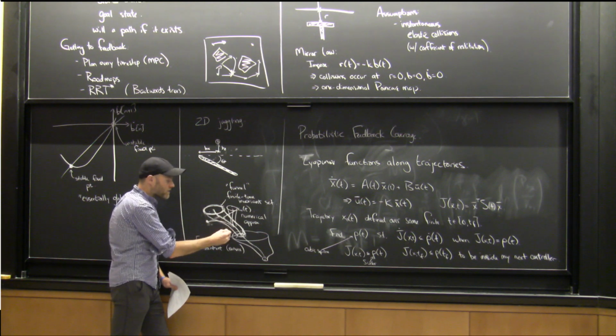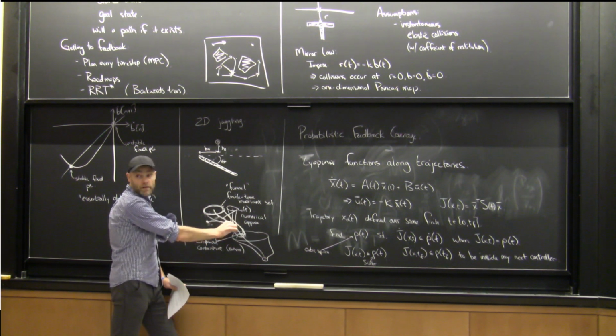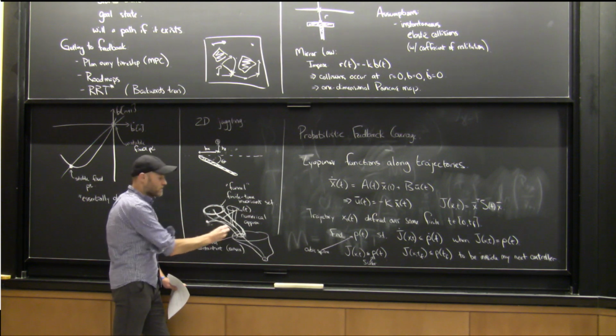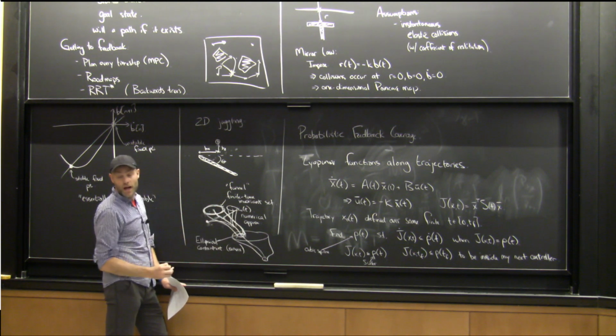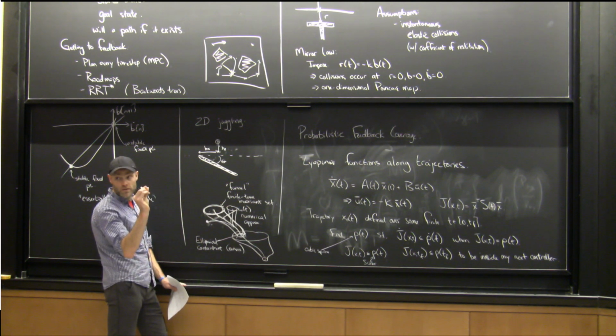But more fundamentally, I think that you don't want to be just at the edge of the trajectory. You want to somehow land in the middle of the funnel so that your controller has some margin in order to land. So landing in the middle of the optimized funnel seems more natural. The burden, though, is it means the RRT's completeness comes from the fact that you're eventually adding arbitrarily short trajectories.